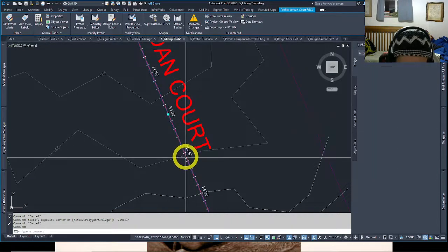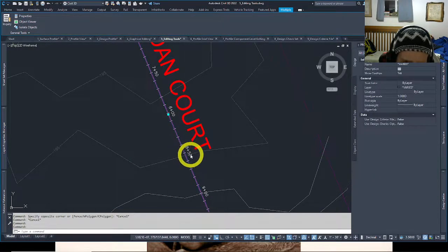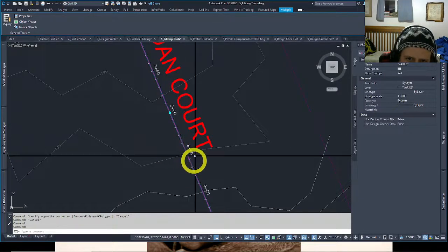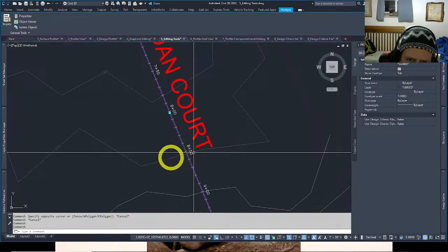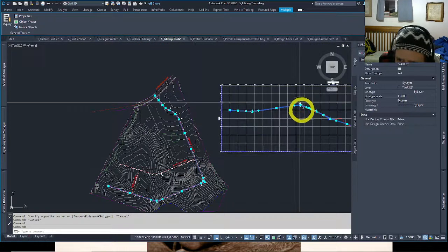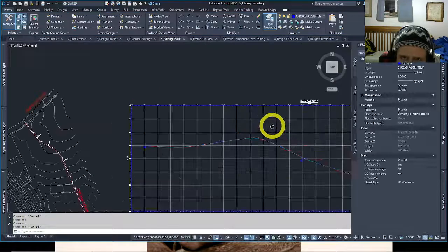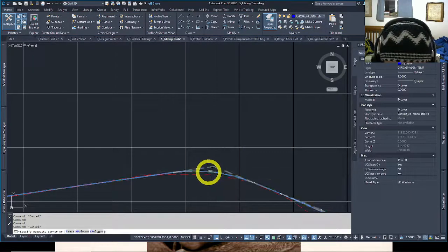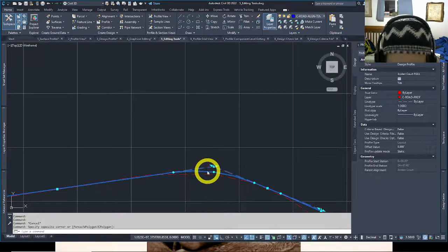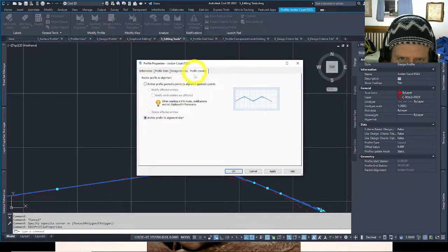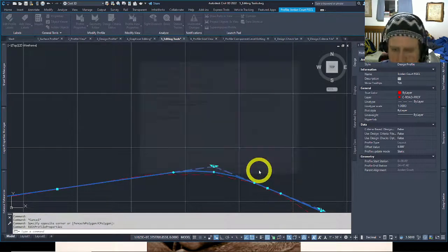They would be locked positionally somewhat between each other. So it would almost be like there's profile information in here that can't be touched, that links this position with this position. So it's just a way to interlink them. I'm going to turn it off for now. Go the other direction by right clicking, go to profile properties, profile locking, it's off. Okay, I'm just making sure.